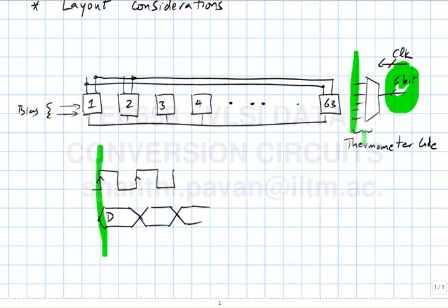Another practical issue is whenever you have combinational logic, it is very likely that for some specific changes in the input digital code, there will be glitches in the output. So you would expect, for example, when the data changes from some code 7 to code 9, you probably expected some control line to do, say, this.